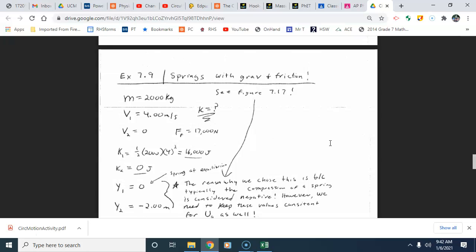Because if you're developing something like this, you don't just manufacture a spring and say, well, I think this is going to work. If all else fails, if it's too strong, if it has too high of a spring constant, it's still going to be like hitting a brick wall, or a concrete floor. But obviously, if it's too low of a spring constant, the energy from the fall when it hits it could just completely collapse it like it's not even there, and you would still hit very hard. It has to be a spring with the constant that is able to absorb the amount of calculated energy that could possibly happen if everything else fails. So that's the situation we're finding here.